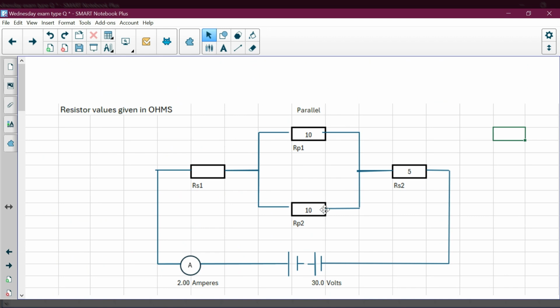At which point I could have calculated power taking I squared times R. The current flowing through here is 1 amp. So 1 ampere times 1 ampere is 1, and then times 10 would have given us the same 10 watts. Okay, so there's multiple options that we could utilize to calculate the current through each one of these branches. Hope that helps.